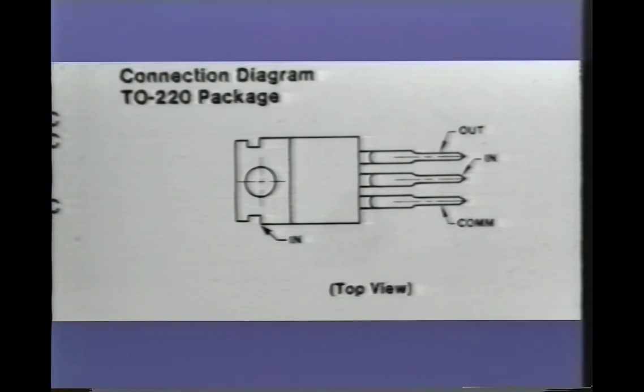And again, we have another set of part numbers that you might see used as a substitute. They're the LM320 series, and the last two digits indicate the voltage of each of these regulators as well. Negative regulators are not interchangeable with positive regulators. Notice the difference in the connection points here. The output pin has remained the same, but the input and common leads have been reversed. Notice too that the tab of the device is now the input of the regulator.